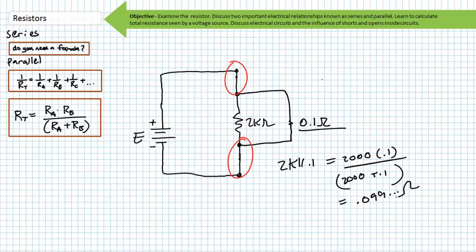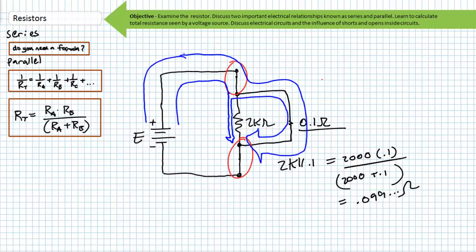And if the resistance is low, the opposition to current flow is low. In this case, current could potentially surge to dangerously high levels, in which a majority of it travels through the short, and a small predictable portion of it passes through our 2 kilo ohm load. Again, errant low resistance paths in the form of shorts are to be avoided at all costs because they allow for low resistance or low opposition paths and incredibly high currents.